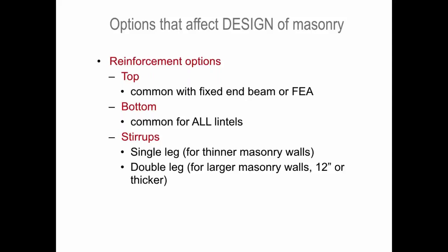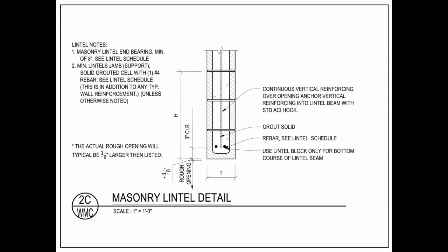Lastly, down there, stirrups. Stirrups are an option. Sometimes people will be like, I can't put a stirrup within a masonry wall. Well, it depends, right? We need to be careful about how much and what thickness of wall we're talking about, but stirrups can be used in some of those limited depth scenarios if we have pretty heavy loads we're designing for. So pretty typical layout reinforcement here.